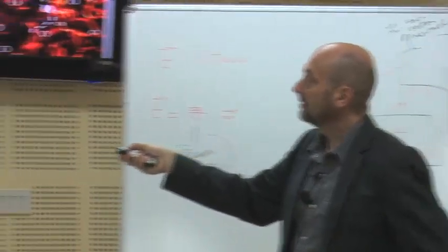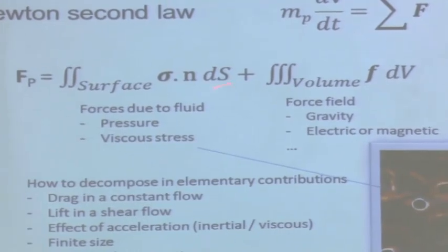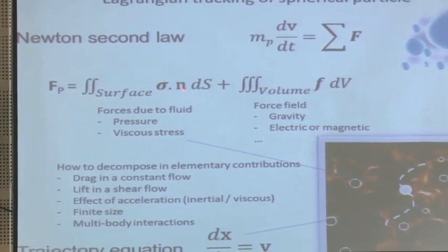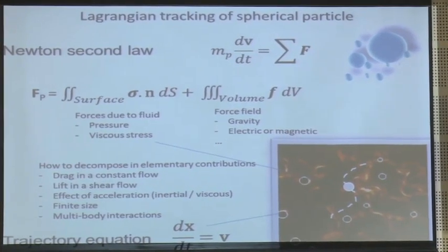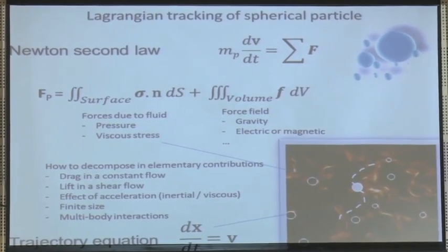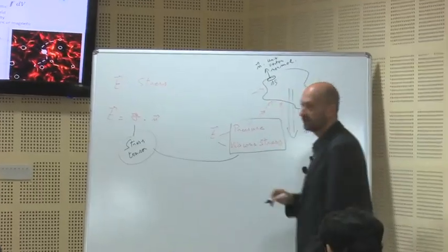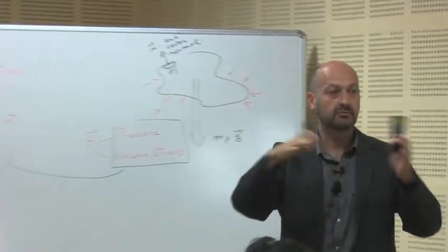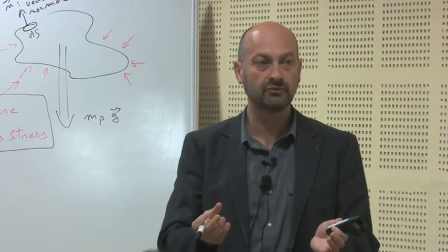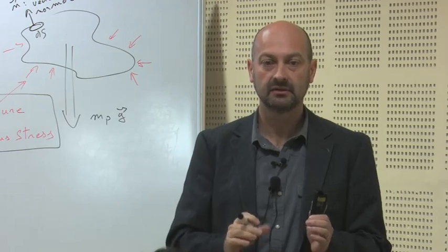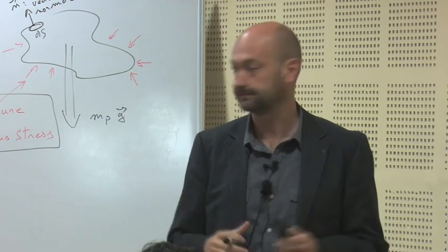So if you integrate this stress over the surface, so sigma n is a stress, you multiply by your surface of integration here. Here you have a small surface, which I call ds. And if you make the summation of all these stresses acting on small surfaces ds, then you will get the total force.